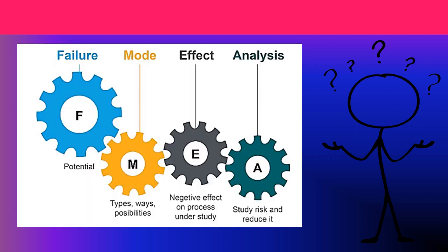It is developed by a cross-functional team. The size of the team depends on the complexity of the design and the size of the organization of the company. FMEA development is also meant to be before the event and not an after-the-fact exercise. And this upfront review and completion of FMEA protects you from any crisis situation later on.